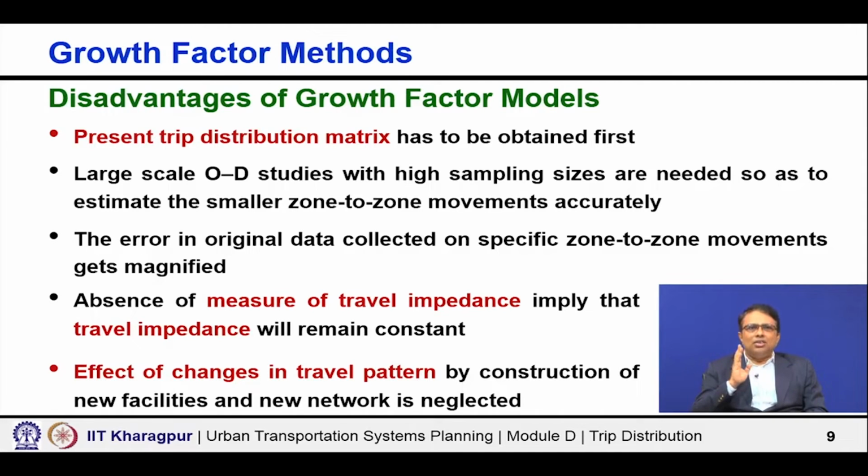Second, large scale OD studies with high sampling sizes are needed so as to estimate the smaller zone to zone movements accurately. Somebody needs to give you this; where will you get it from? In the field you have to measure. So, you need large scale OD studies, okay, to capture all the movements with the required accuracy and to get a proper sample.